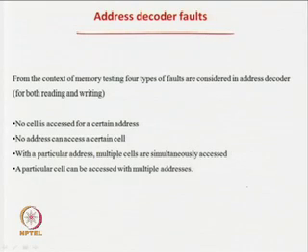There are actually two other analog parts in the circuit, as I told you: the sense amplifier, which sends the values from the circuit, and something which drives the value to write a memory cell. So those parts will not be tested explicitly, and similarly the decoders will also not be tested explicitly. The idea of the memory decoder is that you select some cell, you write it, and you retrieve it back. So this decoder should be able to select the cell properly. That is the idea.